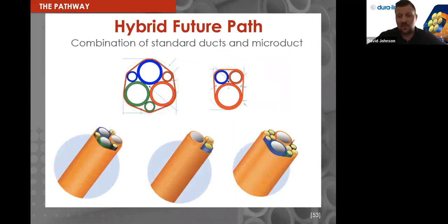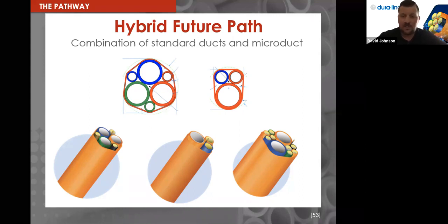We also enhanced that, and we went with a hybrid FuturePath configuration. This hybrid FuturePath configuration has been a huge seller for us in the last 2 years. Because there's customers that want high density, they want to use armored fiber, but they want to start incorporating microducts maybe for small cell sites or for drops. So the hybrid FuturePath consists of standard conduit and then microducts. Or we have hybrid FuturePath that's 2 different sizes of microducts, right? So it's really just emphasizing 2 different sizes of pathways bundled in an oversheath.